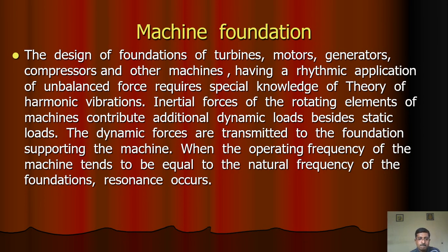resonance occurs. So when you are designing the foundation for machinery or equipment, all the dynamic forces will have to be considered, especially the impact forces and oscillations of the machine. The reciprocating forces are also there. So all these forces will have to be considered in the design of the machine foundation.